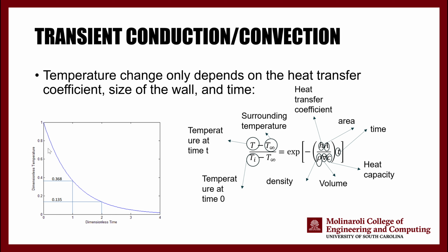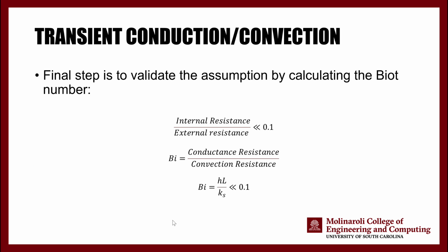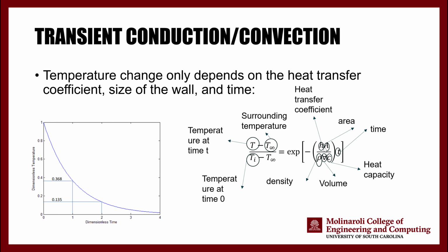Essentially, there are going to be two scenarios. In one of the scenarios, we're going to put a fan in front of your specimen to simulate forced convection, and then another specimen is just going to be left dangling freely, and we're going to see the rate of the temperature drop. And using those two data sets, you are going to calculate the heat transfer coefficient.